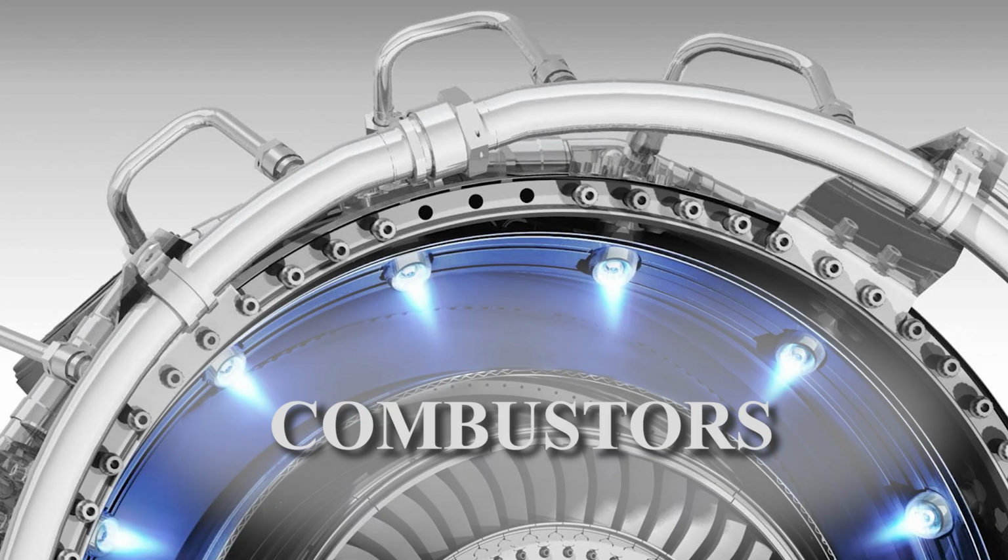Early gas turbine engines used a single chamber known as a can-type combustor. Today, three main configurations exist. They are can, annular, and cannular, which is also referred to as can-annular or turboannular. Afterburners are often considered another type of combustor.